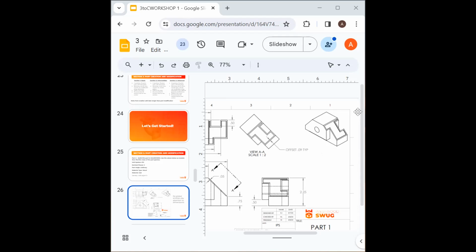Okay. So now I'm going to offset entities. I'm going to dimension it to be 0.09, and I'm going to reverse it. So you notice that it moves. That's fine, because then you can double click on this dimension and alter it to be 0.09. And now we create that shaded region, right? And we're looking for that shaded region so that when we click on it, we can cut through.